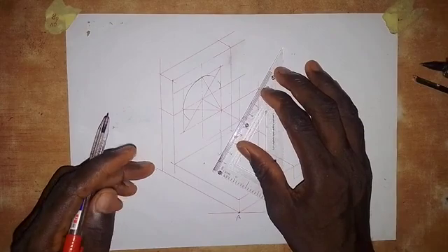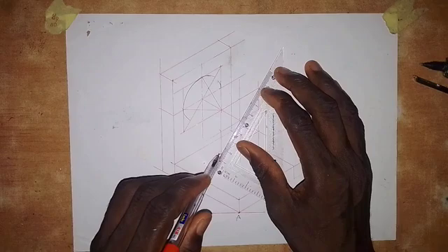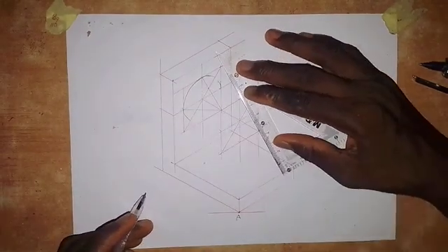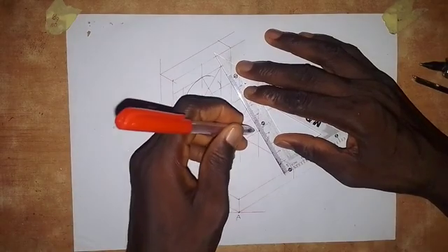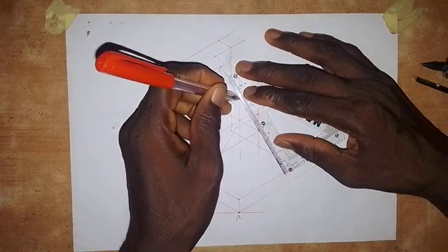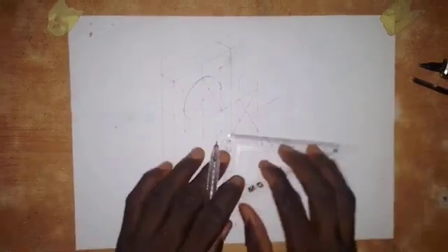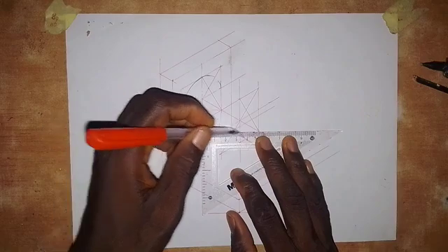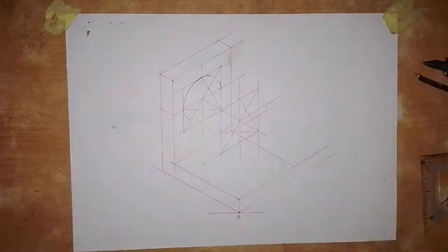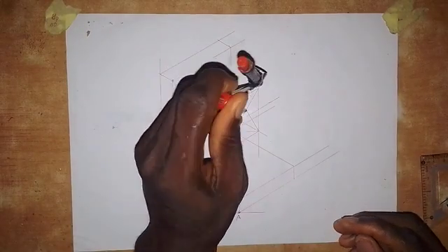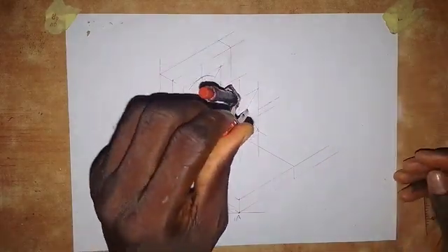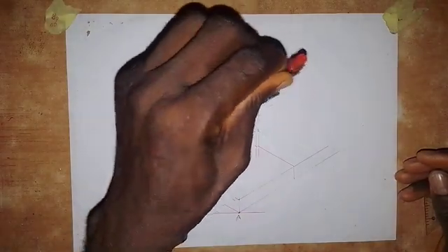Here we are going to draw a complete isometric circle. So we join the longest corners together like this. Then we connect this point to these 2 points together. Connect these 2 points together, and then connect these 2 points together, and then we take the compass. Putting the pinpoint of the compass at this point here, we extend it to this point, and then we draw an arc. So it goes like this.